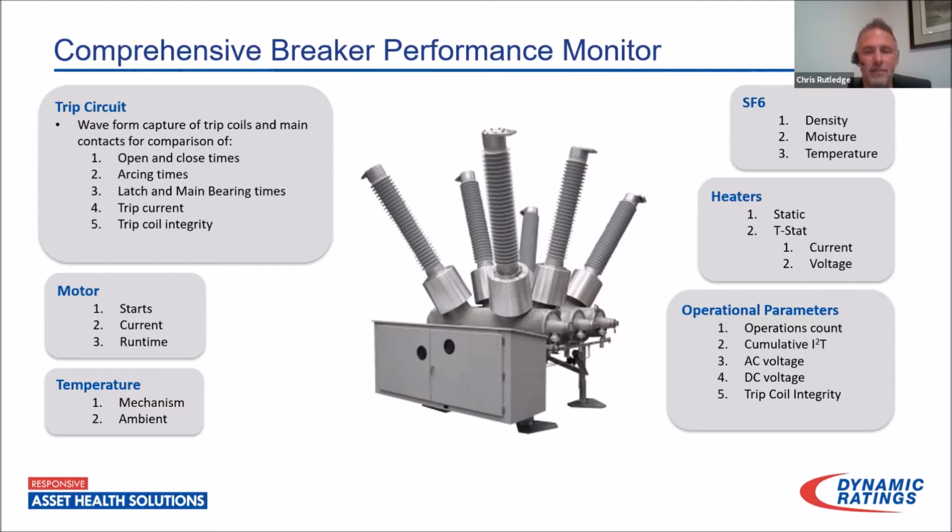With hydraulic and pneumatic mechanisms, you're able to set a value to that, which will let you get an alarm after excessive runs. So let's say for your breaker, 1 start per day is the normal for your hydraulic or pneumatic mechanism. You could set that value at 1, at which point, if you started getting 2 starts per day, you would get an alarm in. We also provide alarms for hydraulics motor runs, generally on both the open and close. If you don't get those motor runs, we'll provide an alarm on that as well. So it's very comprehensive when we start talking about how the motor's running.